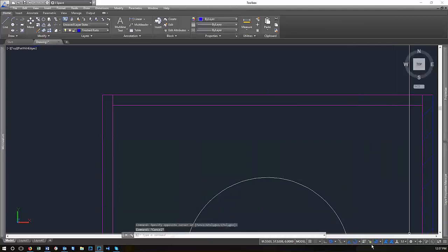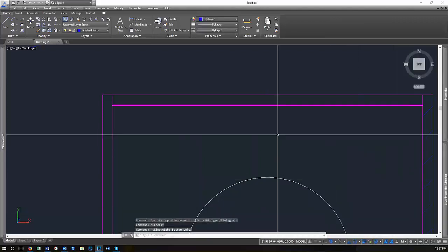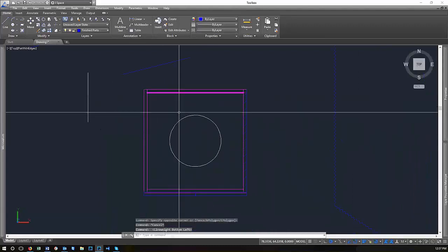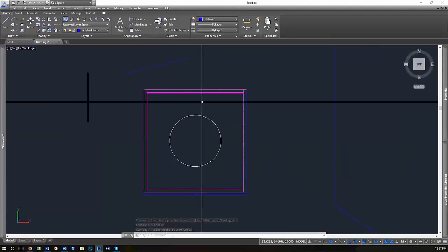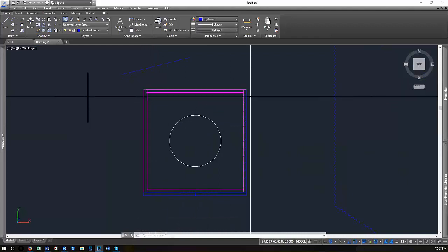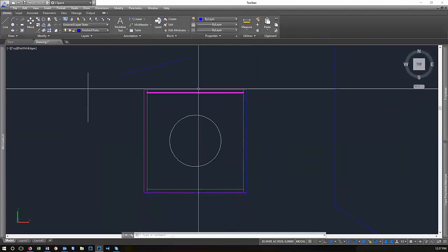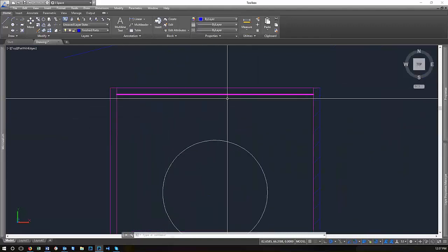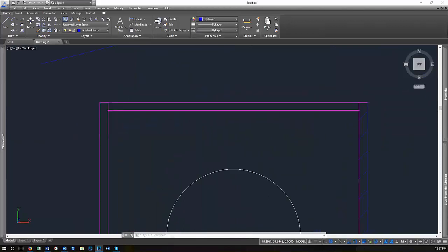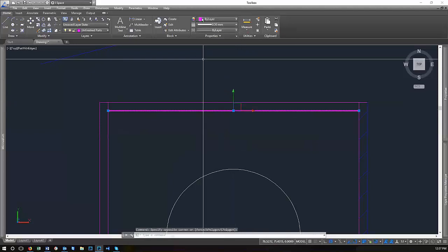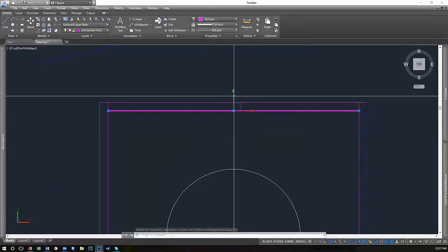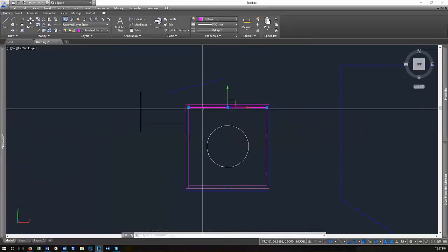So I've turned on to be able to see line weights now. I typically don't have that on because I want to see just the straight lines, and since my plot styles determine that anyway, and I use layer states to manage the assignments for color and for line weight, I just use color to show myself what line weight it is.